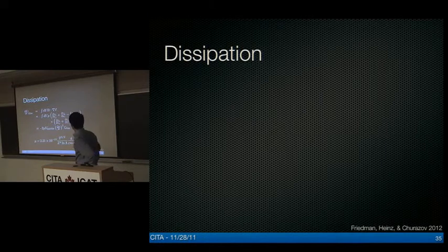Okay, well, all you're really doing in this case is taking the equations and making a dimensional analysis, and then numerically calculating, in post-processing of our simulations, an efficiency of viscous dissipation. Now I should say that the simulations were implicit in the sense that they didn't have any extra viscosity in addition to numerical viscosity, which of course is artificial. But we can still calculate in post-processing, just from the calculated velocity field, what the viscous dissipation rate should be. So the viscous dissipation rate should just be of the order of the bubble volume again, times essentially the velocity gradients squared times the viscosity. The viscosity factor here.